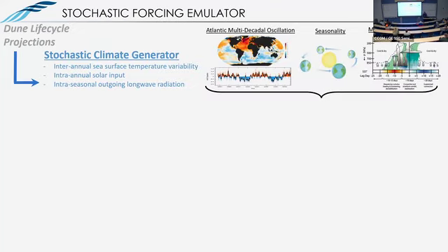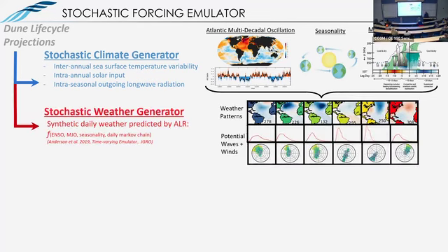So how we've been getting around this is starting to think about clever statistical climate emulation approaches. So I work a lot with Dylan Anderson, who's now at the Corps as well. Mostly work coming out of the University of Cantabria and Oregon State University in terms of thinking about statistical representations of climate forcings at basin scale and how those ultimately relate to weather. So we use, in this case, autologistic regression techniques based on sea level pressure fields, which define weather pretty well. And from that, we start coming up with representative patterns in terms of what weather looks like at a basin scale.